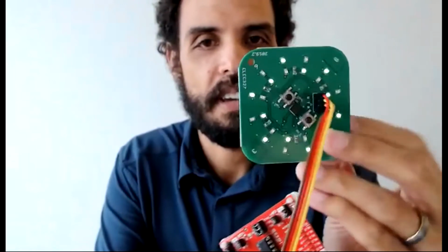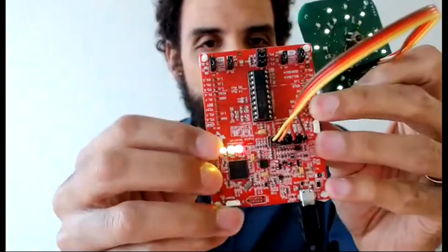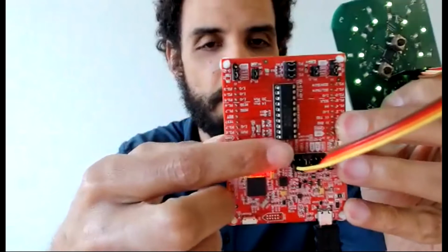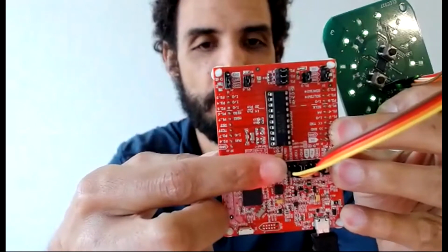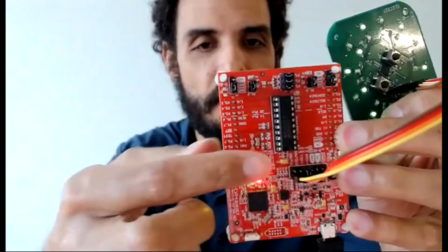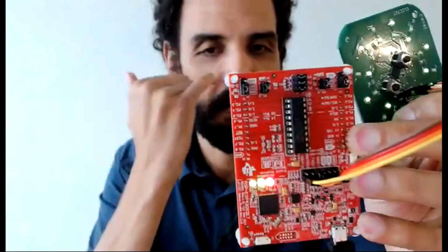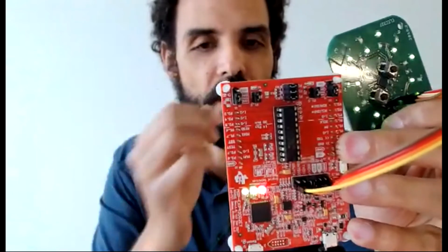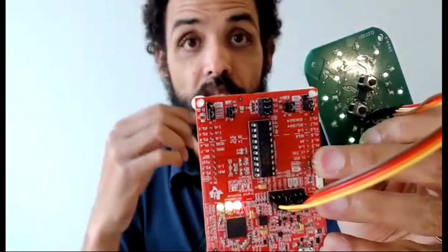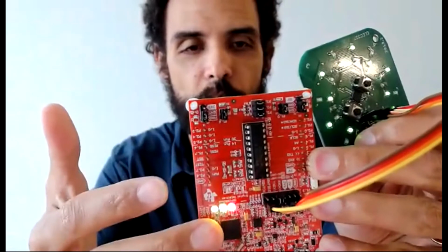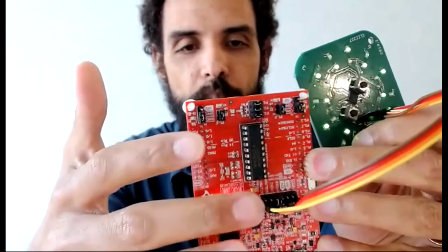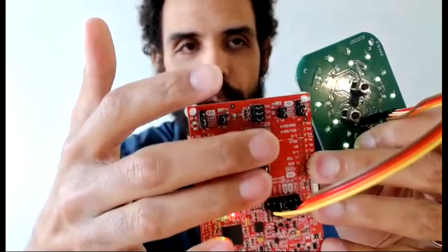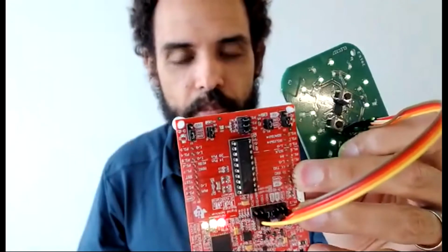Now, those connections are wired up to the launch pad. So you can see that I've removed the jumpers from the pins that are marked SBW TCK, SBW TDIO, 3.3 volts and ground over here. And these are the ones that you use to program a launch pad. So this is the debug interface, remember, and then this is just a simple MSP430 that's connected just by these jumpers. So we disconnect them. So this is not being programmed. Instead, this is being programmed.